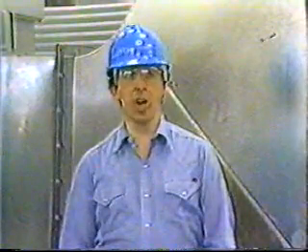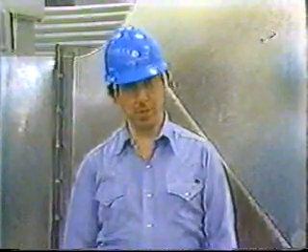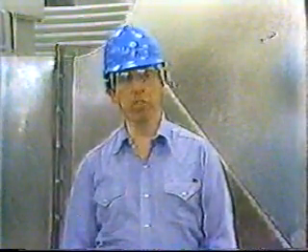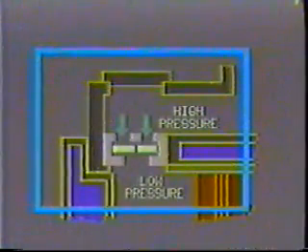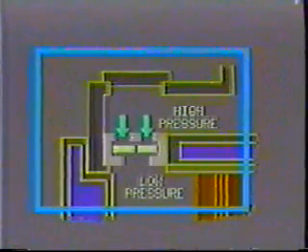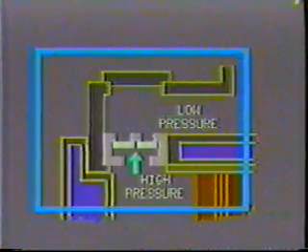Before we discuss the operation of valves, both suction and discharge, there's a very important point that needs to be understood. Both suction and discharge valves are identical pieces of equipment. Their function as suction or discharge valves depends solely on their placement within the cylinder. A suction valve opens whenever the gas pressure inside the cylinder is less than the suction gas jacket gas pressure. When the pressure relationship is reversed, the springs close the valve.